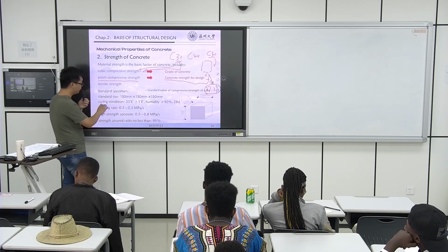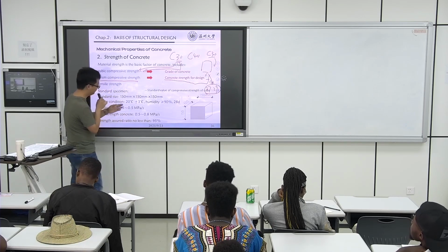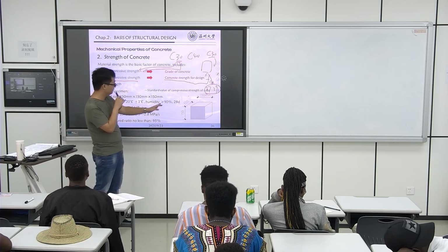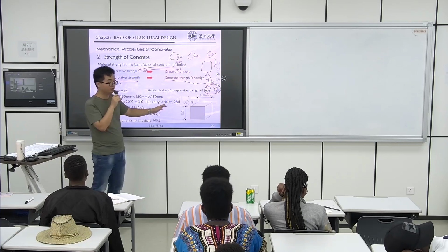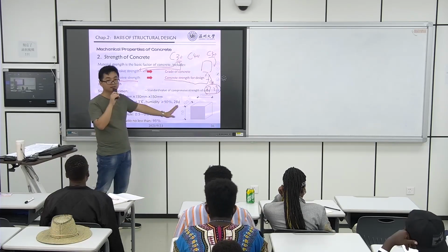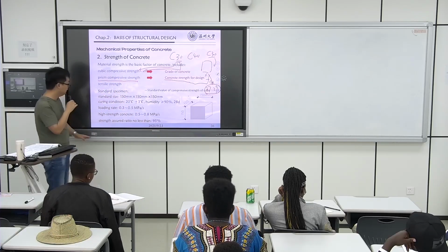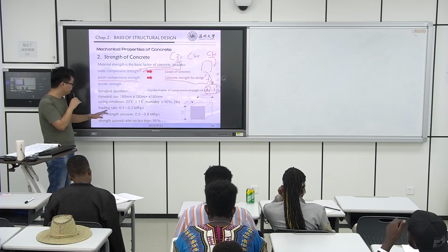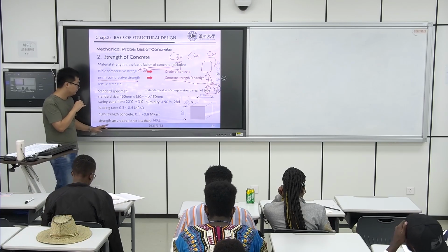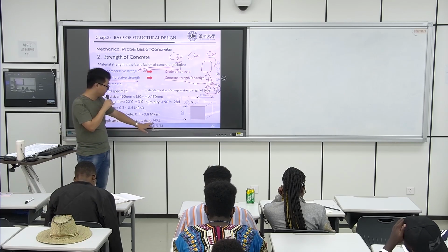The curing condition is at 20 degrees, and the humidity should be larger than 90%. The age is 28 days. The loading rate for high strength concrete, the guaranteed rate is no less than 95%.